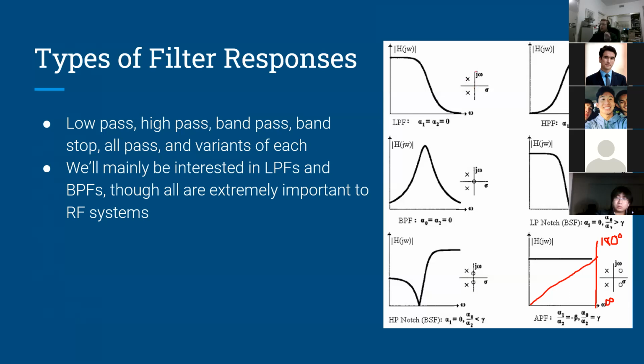So if you're looking along the j omega axis, which is basically frequency, at DC, 0 frequency, right here, we're right in between the 2 poles, and those poles are going to prop up the frequency response, allowing signal to pass, which is what's indicated in the filter response right here.